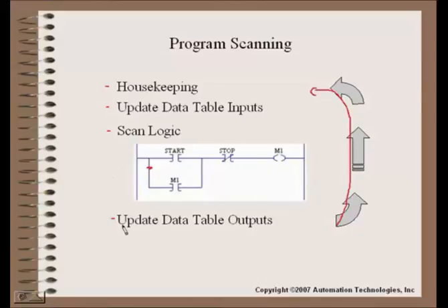This is called the PLC program scan, and a PLC program will scan repetitively as it's running, constantly updating its outputs and constantly checking its inputs, and that's the important thing to remember about programming in a PLC. PLC program scans are very quick. You will see them on the order of milliseconds and microseconds. So we're looking at information that's being processed very quickly, and it obviously has to be able to monitor relays and monitor encoders and other fast-acting devices out in the field.